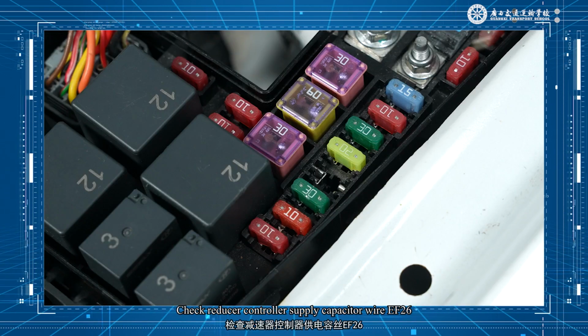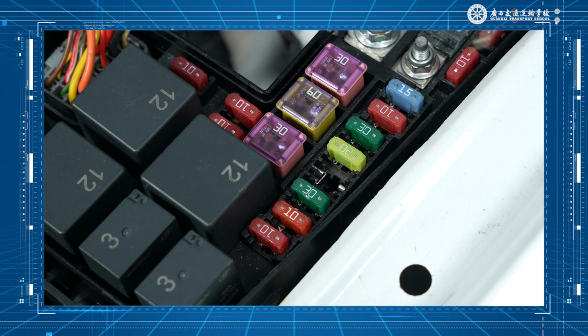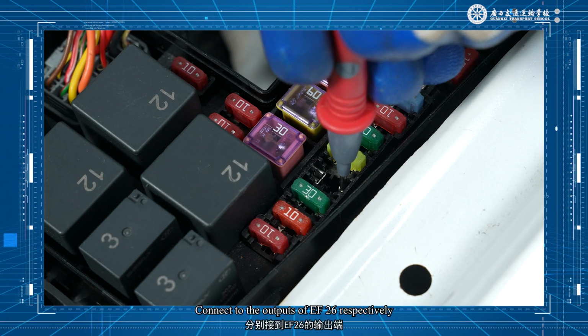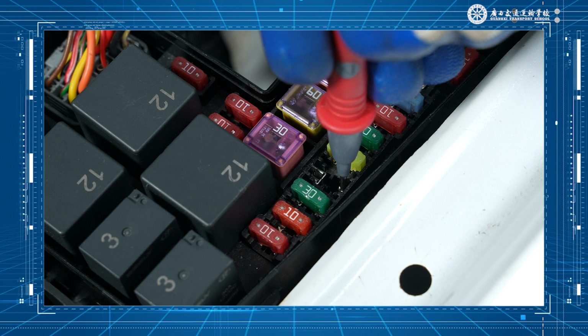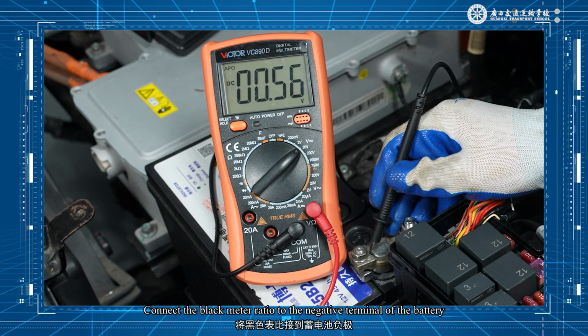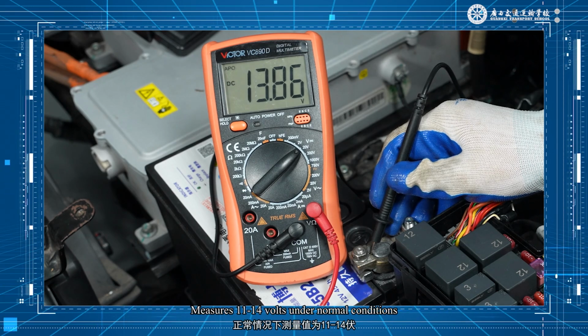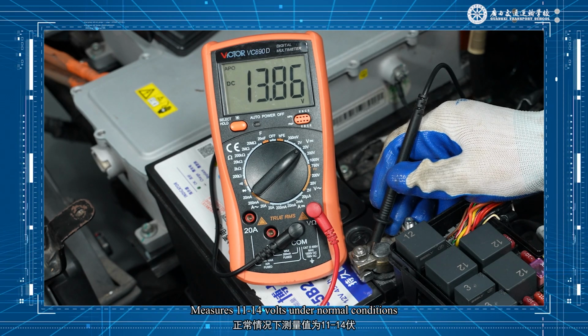Check the reducer controller supply wire EF26 output voltage. Connect the red pin to the output of EF26. Attach the black pin to the metal housing of the bodywork. Read the DC voltage value. It measures 11 to 14 volts under normal conditions.